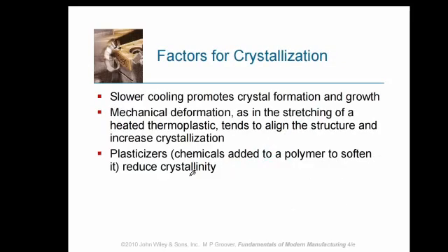And mechanical deformation, in the stretching of a heated thermoplastic, tends to align the structure and increase crystallization. And then sometimes plasticizers are added to reduce crystallinity.